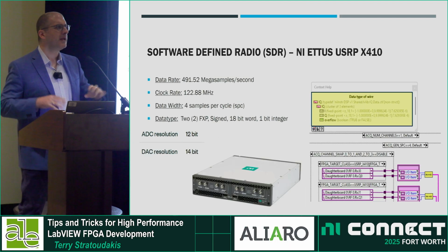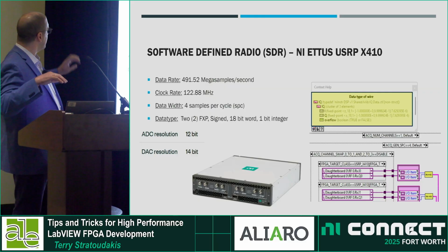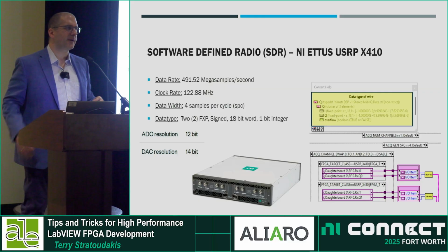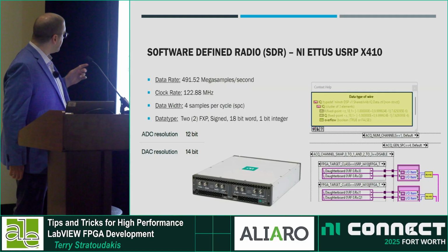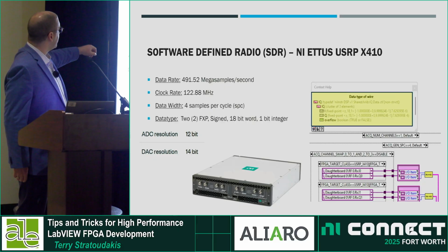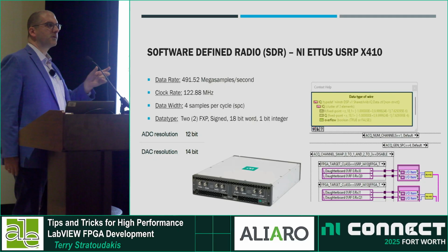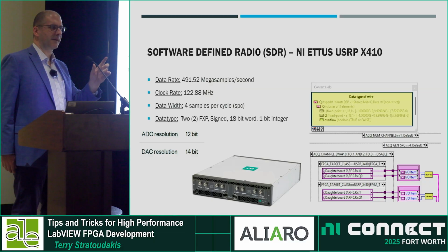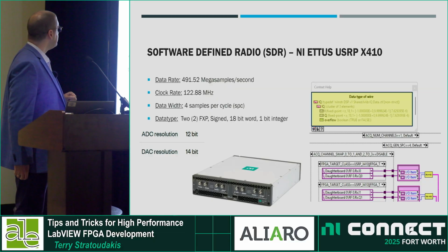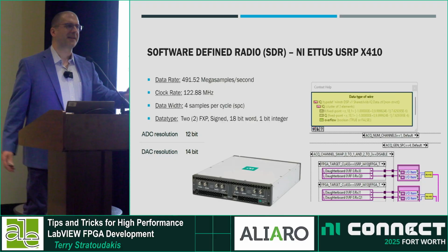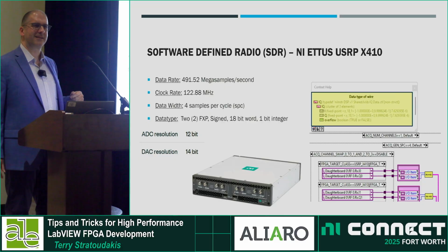And this is the last one. Again, just to give you a sense, this is an X410 software-defined radio. This here is running at about 122 megahertz. We're getting 4 samples per cycle, and each of those are IQ samples. So that's yet another different interface that we're seeing.